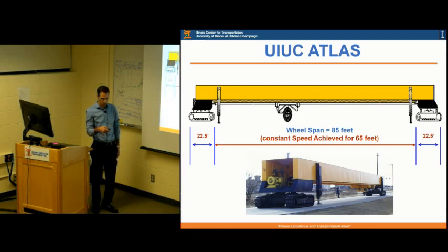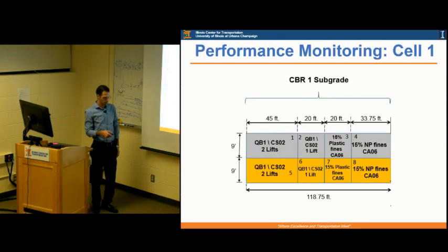So the sections on the side are a little bit larger because some areas here are for the crawler, and some areas here are transition zones where the wheel is gaining speed before it goes up to the 5 miles per hour in the middle. So you have the crawler area, you have the transition zone, then you have the actual section, and then another section, and then another transition zone in the middle to reduce the effect of different sections contributing to other sections. And the same thing on the other side.